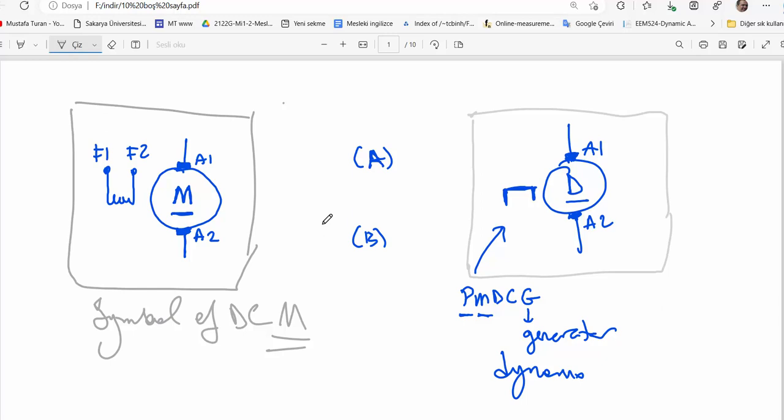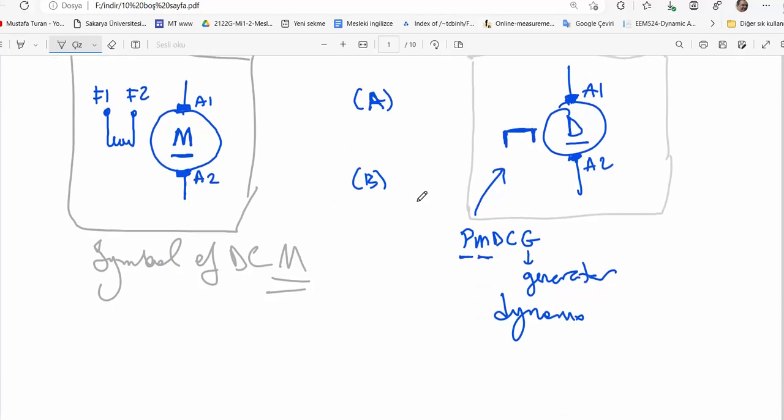In fact, a slightly different design will help commutation. We will talk about it later. Only the brushes are at a slightly different angle. Let's say the brushes are here in generator operation, but if you change the angle of the brushes, let me say that is the commutator, with brushes like this, there would be a smaller arc, so commutation will be easier.